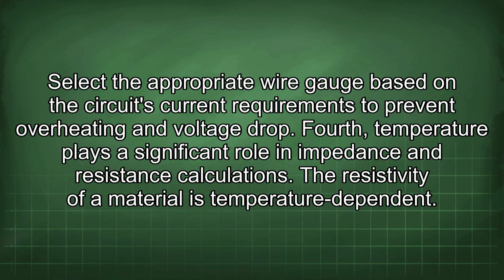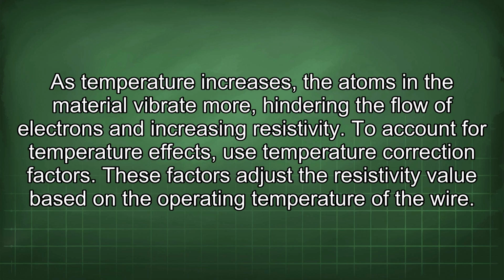Fourth, temperature plays a significant role in impedance and resistance calculations. The resistivity of a material is temperature dependent. As temperature increases, the atoms in the material vibrate more, hindering the flow of electrons and increasing resistivity. To account for temperature effects, use temperature correction factors. These factors adjust the resistivity value based on the operating temperature of the wire.